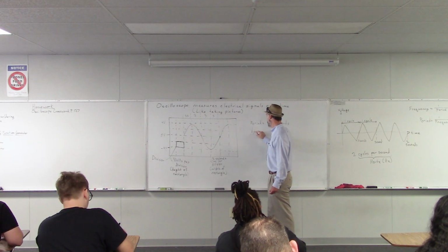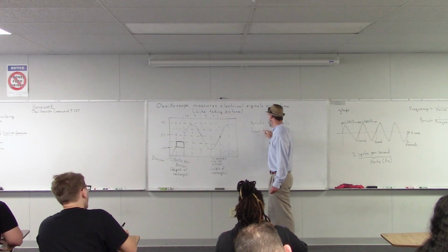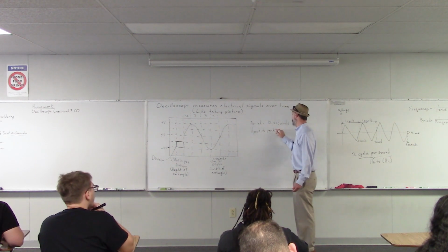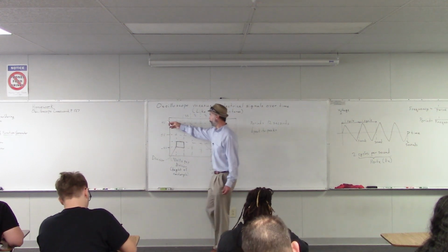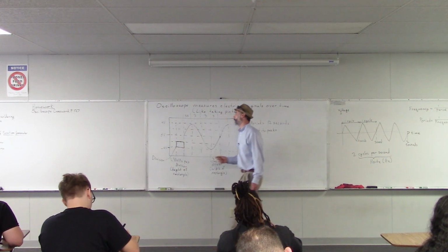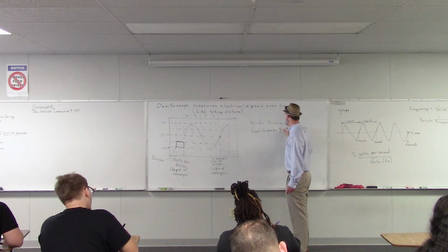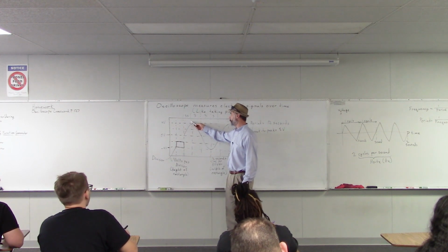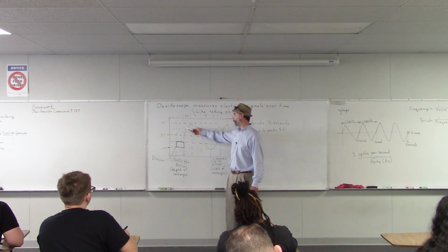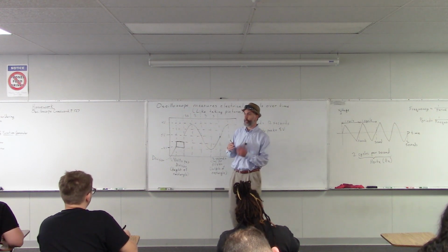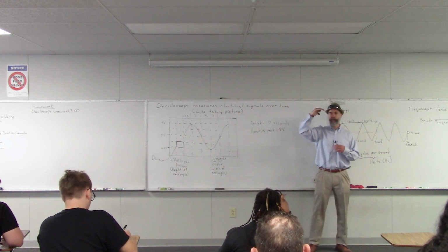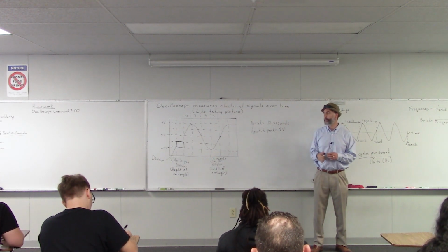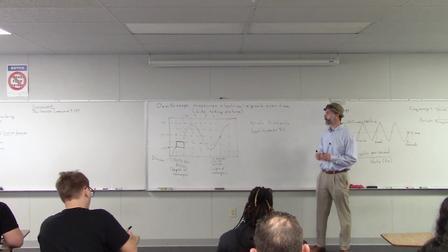Does this have to do anything with sine or cosine? I mean, hold on one second. So V peak to peak here, we're going from 4 volts to minus 4 volts. So that's 8 volts total. So you can measure the peak to peak amplitude of any signal, whether it's a sine wave or a triangle wave or a square wave. The peak to peak amplitude is just the voltage from the highest peak to the lowest peak. Okay? Yeah. So would that technically be the total voltage of your circuit?